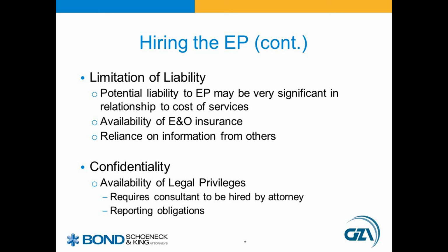This is usually more of an issue in the course of an invasive Phase 2 investigation than a Phase 1 investigation. However, it is always possible that someone walking the site may come across an above-ground petroleum storage tank that is leaking. The prospect of that happening should be covered in the agreement with the current site owner to access the property.